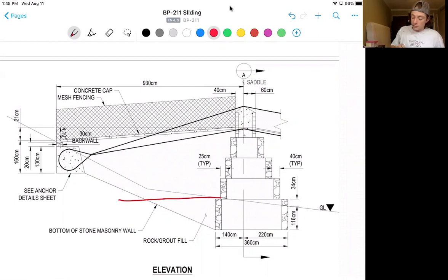So something that we wouldn't do in this case, because we have such a steep slope on the abutment, that if the anchor was down here, we'd have almost 5 meters of excavation we need to do. And with benching, that would be nearly impossible. So one strategy for a less steep bottom slope is to either run it to the top of the foundation or run it horizontal.